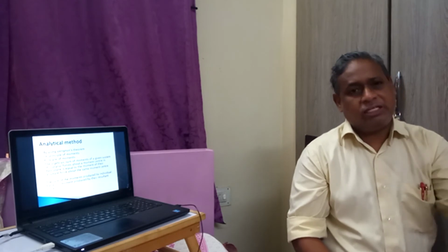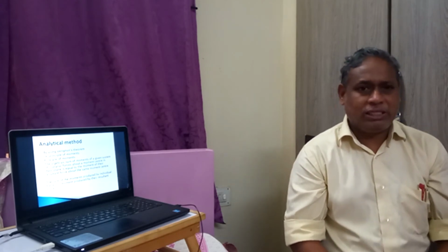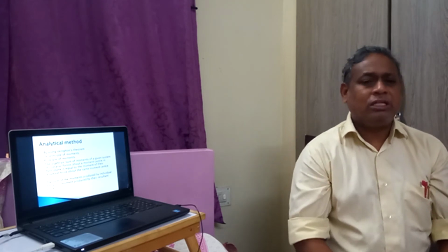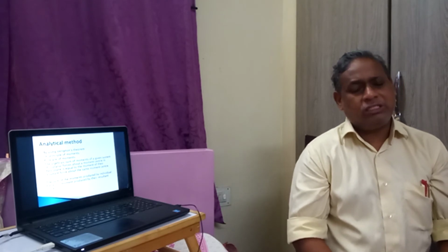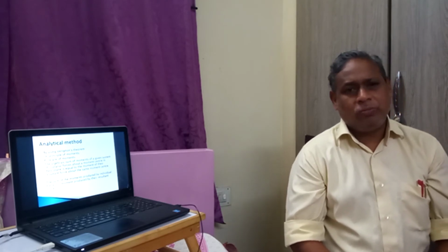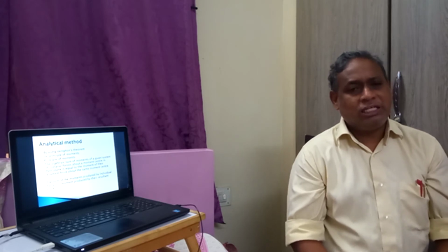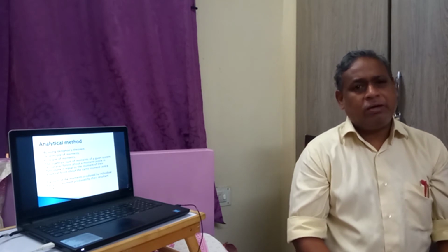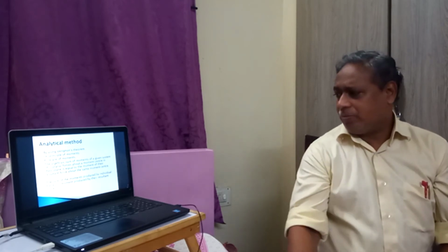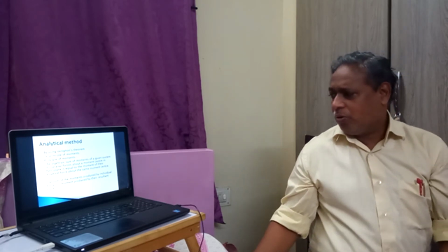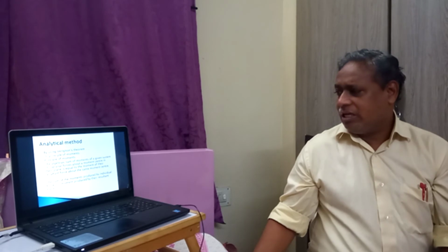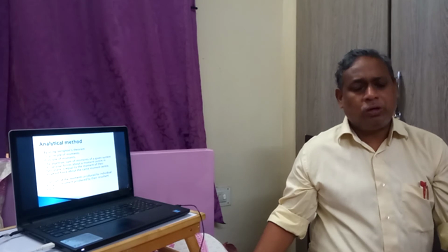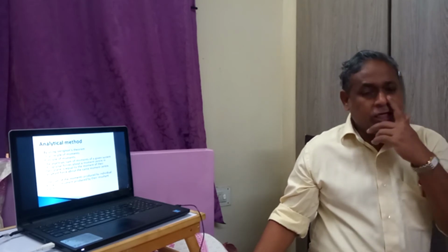Through that moment center, to that axis, if we take the moments of individual forces, that is F1 d1 plus F2 d2 plus F3 d3, and so on, that is equal to the resultant F acting at a distance d. So we can say the sum of the moments produced by individual forces is equal to the moment produced by the resultant force, that is sigma F1 d1 plus F2 d2 plus F3 d3, and so on, is equal to total force F into the distance where it is acting.